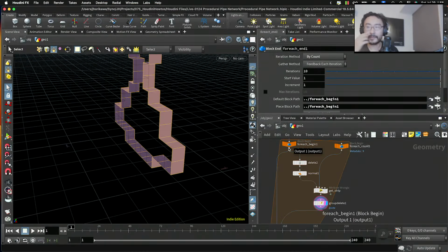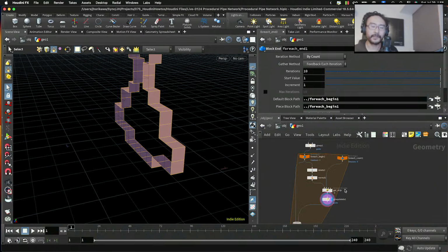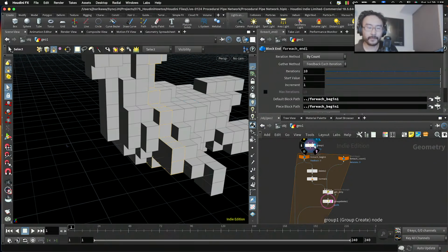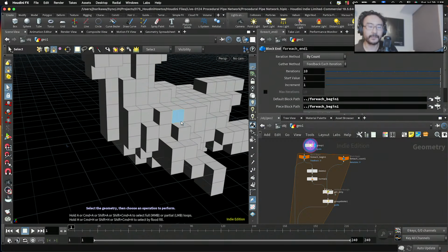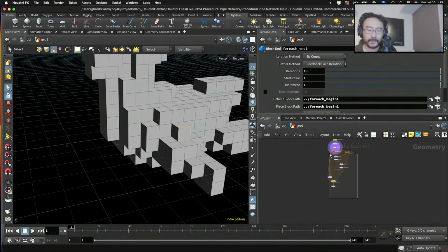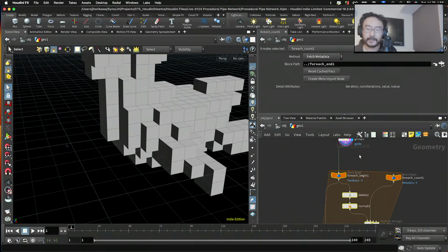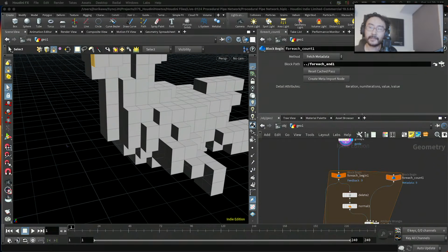And in order to do that, you need to give the original geometry the information of how much each surface has been offsetted by a strip. So to give that kind of information, I'm going to create some additional primitive attributes on the original guide geometry.